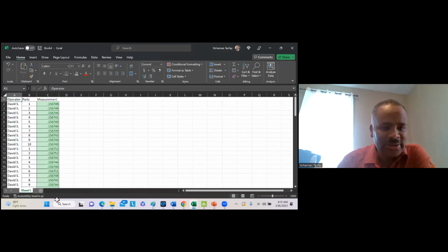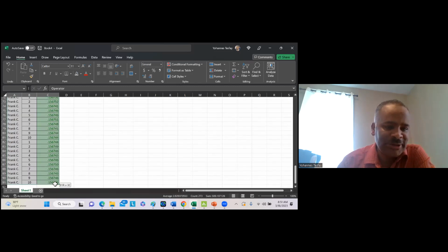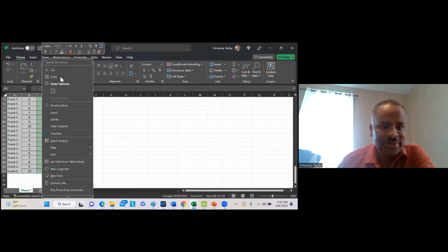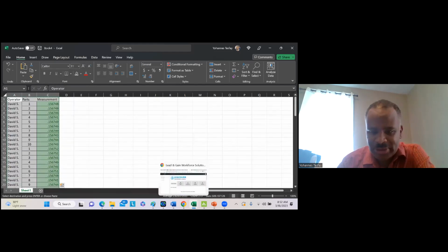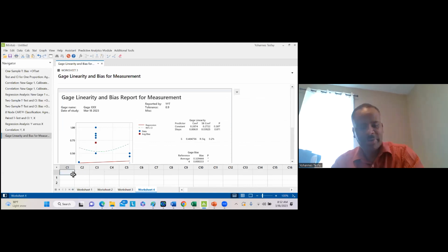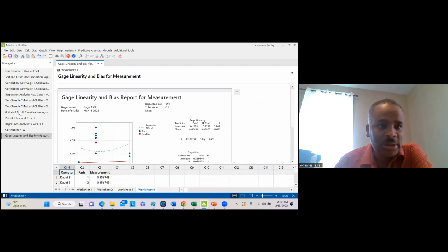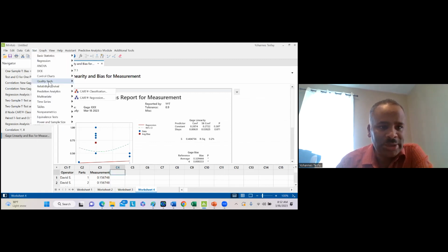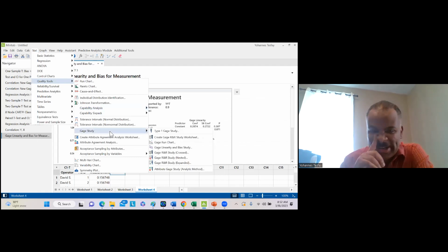So I'm gonna take all this information as it is and copy, then put it in a new worksheet, and I'm gonna put it right here. Like that. So go to Stat. You're gonna go to Quality Tools, Gauge Study, and Crossed. Okay, this is crossed study, not nested. I'll show you the difference between crossed and nested. Then this is Gauge R&R Study Crossed.